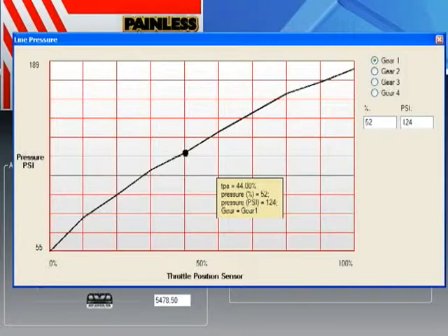Whenever you have a 0% throttle position to, say, 15 or 20%, and someone's just mildly pressing on the throttle pedal, you don't want a high line pressure, because that would cause real rough shifts and squealing of the tires and wear and tear that are not necessary, because no slippage would occur anyway.